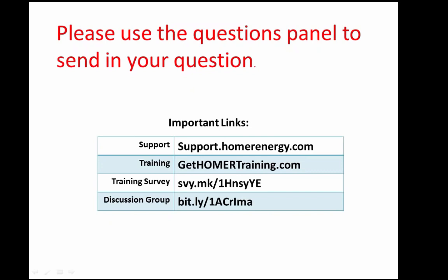Great, thanks. Is scaled wind speed scaled to hub height? Go ahead, Peter. So there's two different issues there. What you're just talking about is what's often called wind shear, and that's handled on the wind resource page. There's a tab that says variations with height. So you can control your wind shear parameters, a couple of different functions for that, etc. So that is handled, but in a different place.